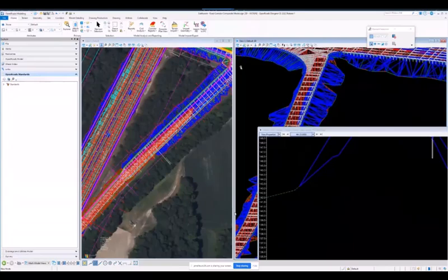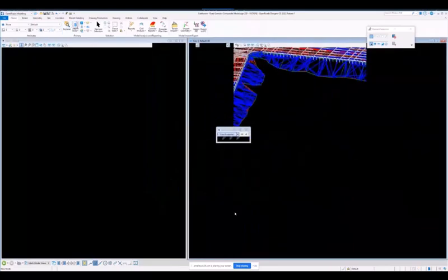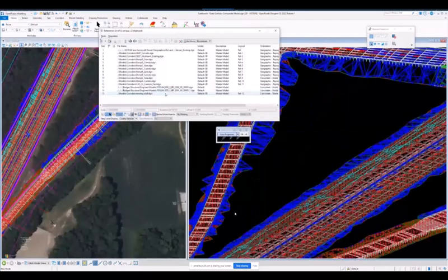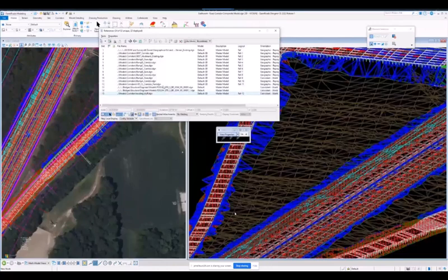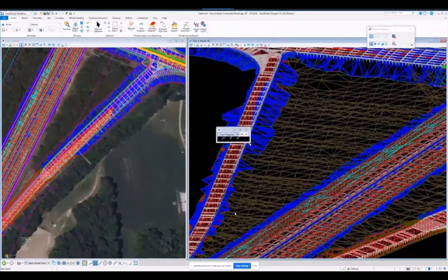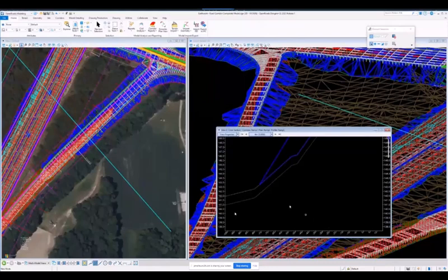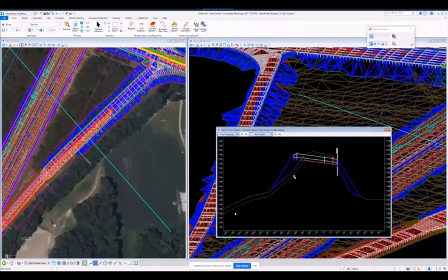But in this case, I'm just dealing with unsuitable, and I totally forgot about it. Well, I could go back in here and, oh, there is my topsoil I created from those infield spots. And I could see in here in the section, oh, I forgot it. Do I have to redesign all those corridors and make overlay templates and deal with that? No, all within that cut fill tool.